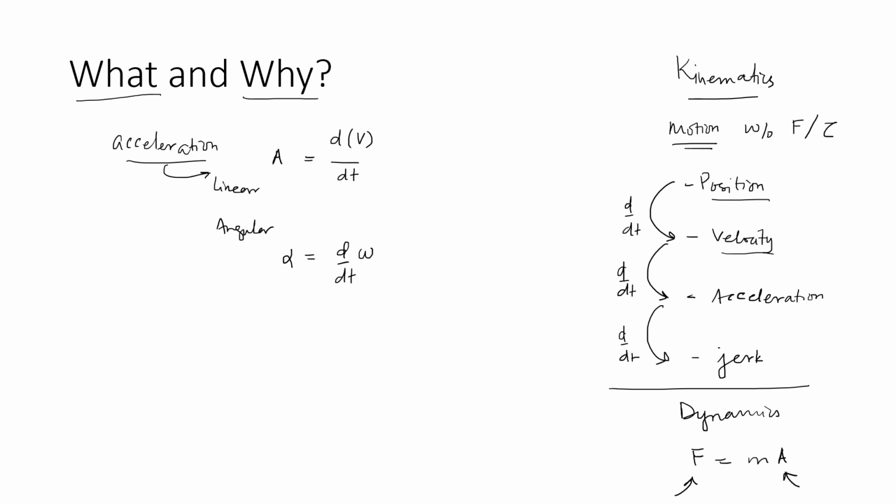So that's why it is important to have the acceleration analysis, because it is going to define how the velocities are changing with time, and on top of that we're going to use that to find out something about the jerk produced during this motion, or potentially if we are doing the dynamic analysis, then how the forces or torques are being generated in this motion.